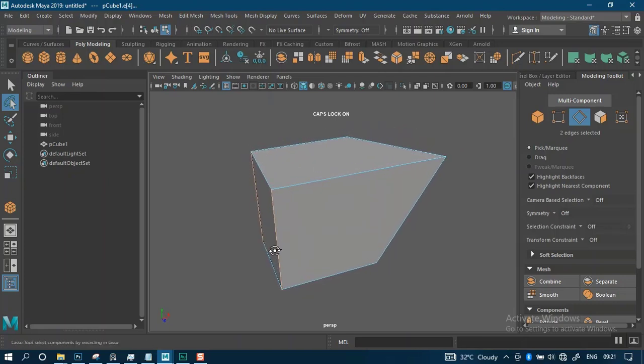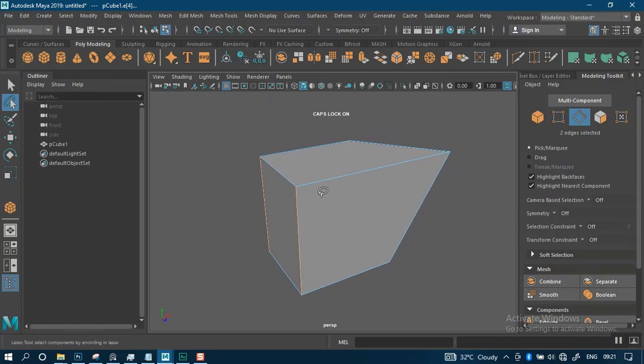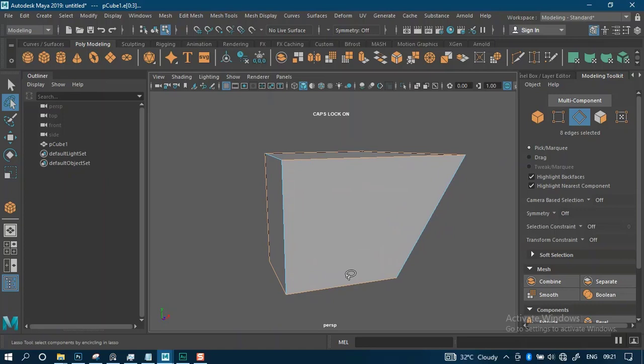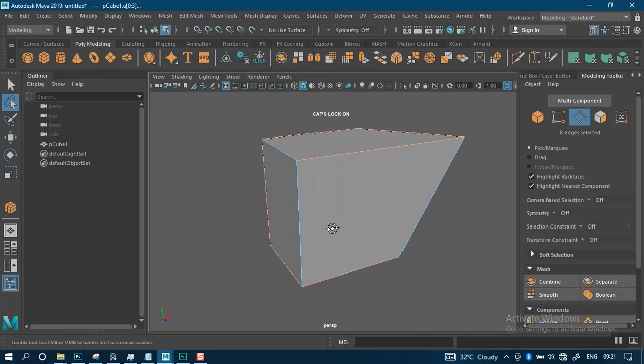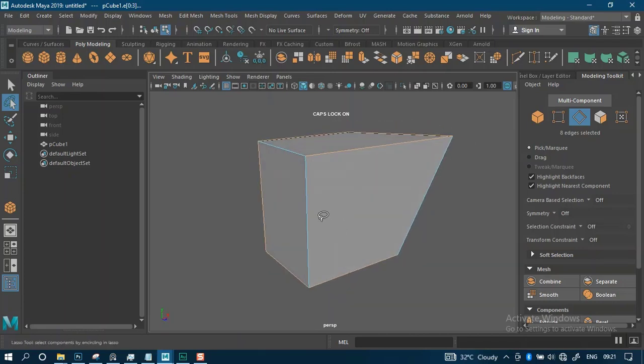To select multiple regions, all you have to do is hold down the shift key, then you can select multiple regions like so. But if you still hold down the shift key and you draw the selection around new selection edges and previous selection edges, something would happen. You would have the previous selection edges deselected, and the new edges selected. That just tells you that holding shift and then drawing a selection around pre-existing selected regions will deselect that.